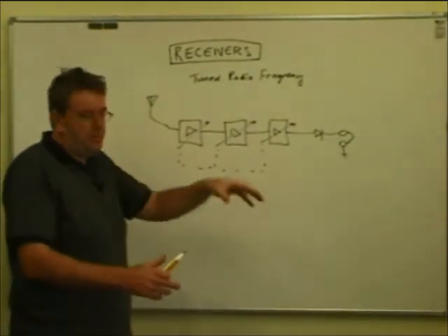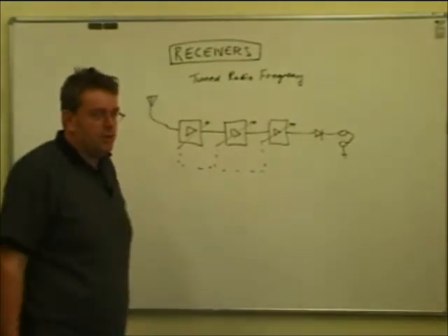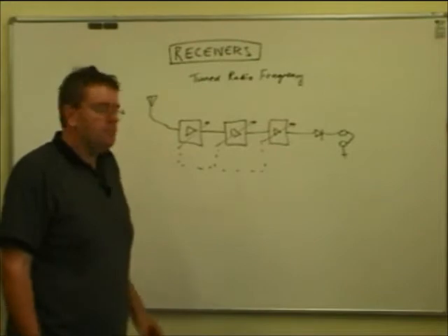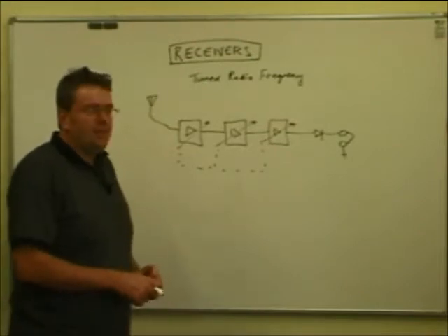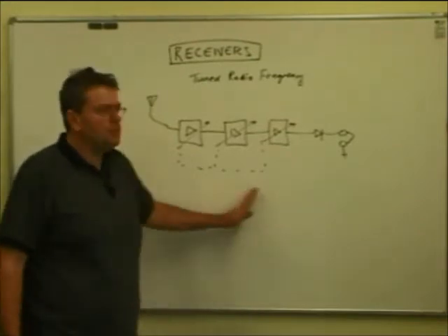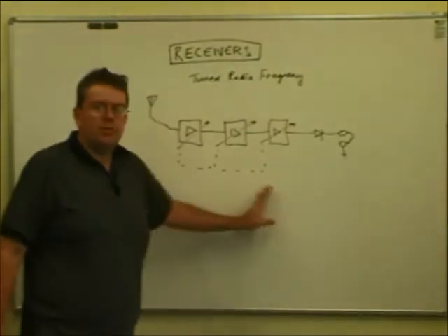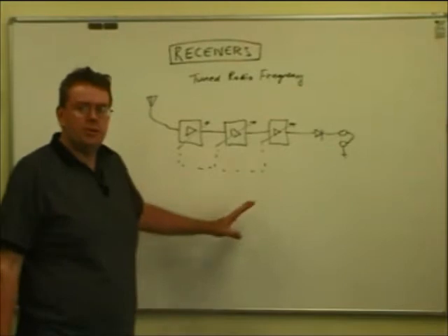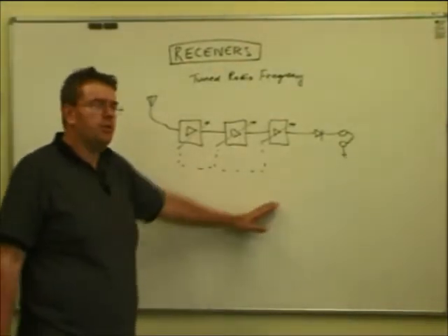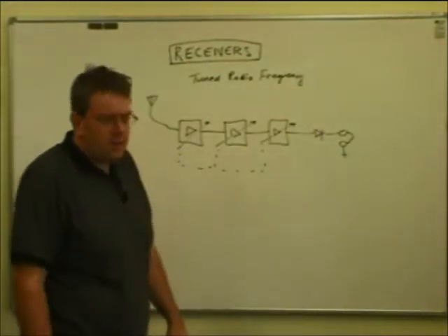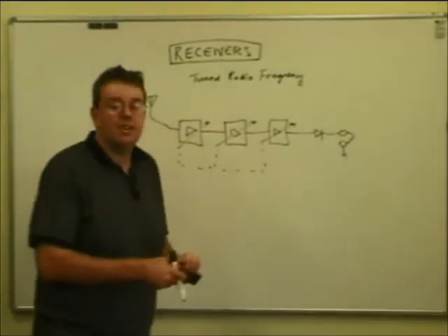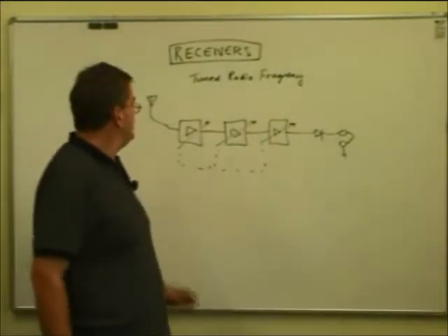Often they had to have maybe three separate tuning knobs in a row, and you had to tune all three to the same point. They worked, but it was a bit fiddly. The other thing too is, as you tune over that wide frequency range, the curve naturally changes, just the way that tuned circuits work, so it might be more selective at the 1600 kilohertz end, but not as selective down the bottom. But at least it put us on the path to be able to have some amplification in the system to receive weak signals, and to have better selectivity.